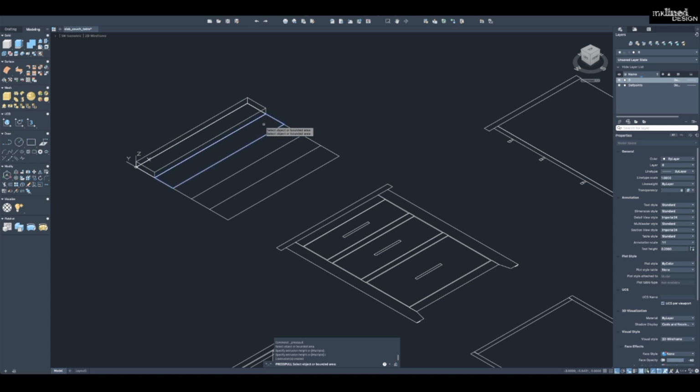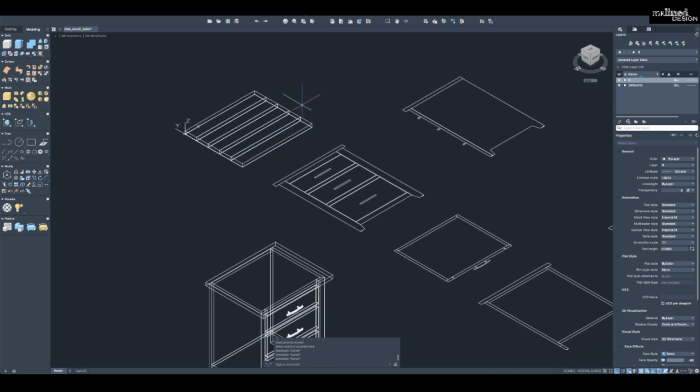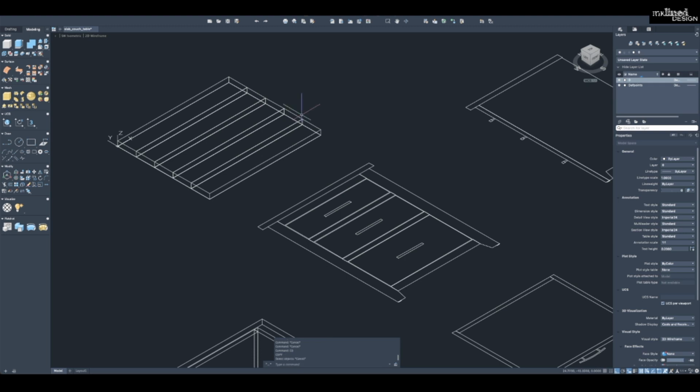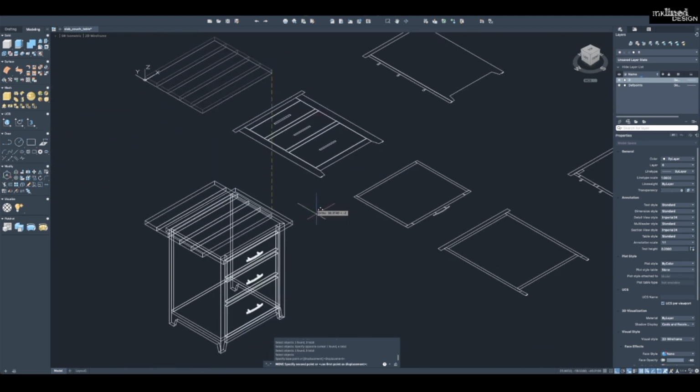And then I'm just going to redo that. So I selected the object, and then I just hit enter, so spacebar to enter, and that pulls the press pull command to the last known height, or last entered height. And then I'm just going to move, and I'm going to select these. So there's a couple ways to move this over to here. So I can leave it